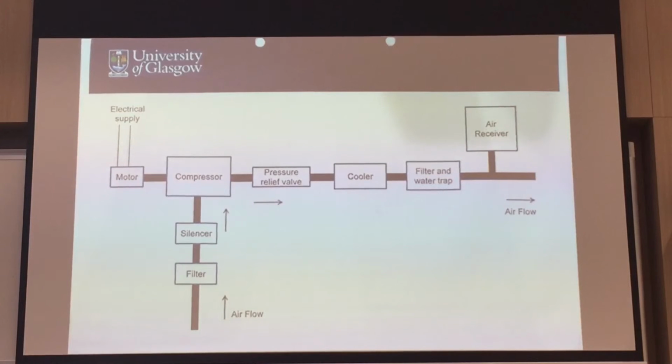So for a pneumatic actuator system, your airflow is going to come in, and because it's your ambient airflow, you need to filter it. And then because the airflow that's coming in that is supplying to the compressor, so there's a gush of airflow that needs to come in in order to supply that amount of pressure. So you need a silencer to come in between so as to reduce the noise. So this part here will reduce the noise because of the large amount of air inlet.